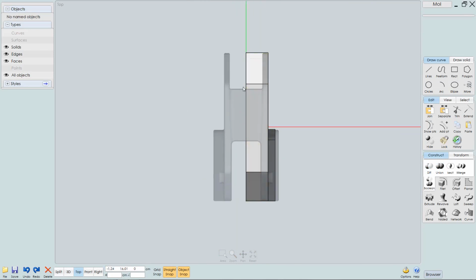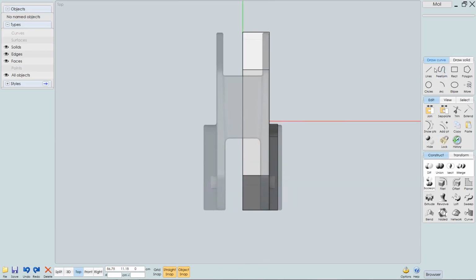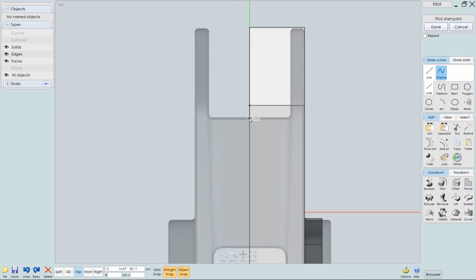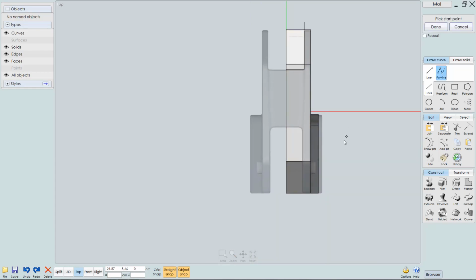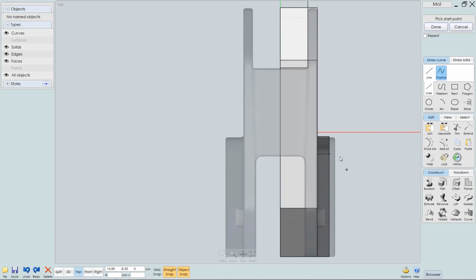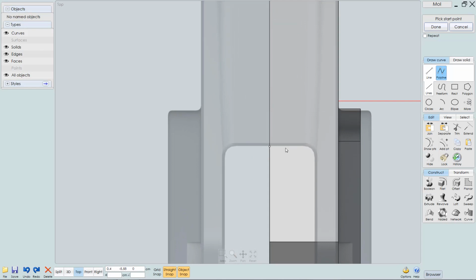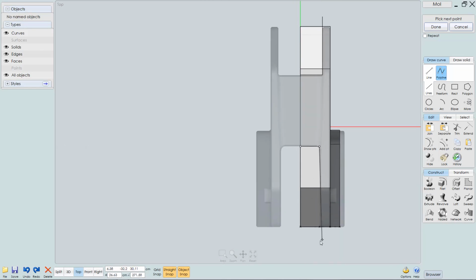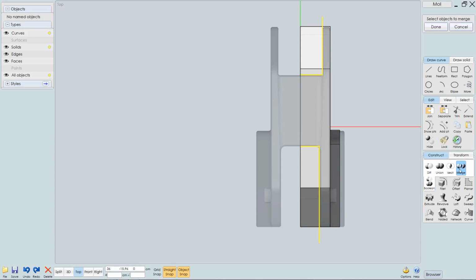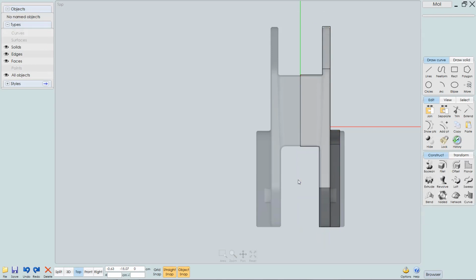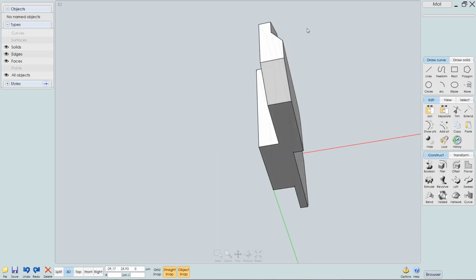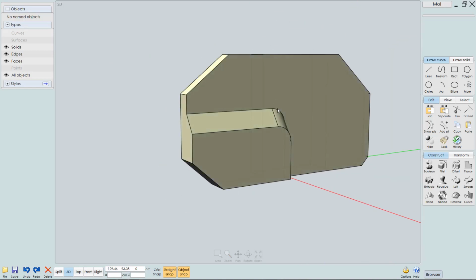In the top view, you can see that we also have some cutouts at the front and at the back. I'm going to create these with polylines again, and I'm going to draw one here. And I can just right click to create another polyline once I've finished the first one. And I'm going to create that curve here at the back. Right click to finish it, and now I can select both curves and the object. Again, do a Boolean merge. Select these parts, the curves are still selected, and I'm going to delete all 4 of these objects. Okay, so that's looking good so far.